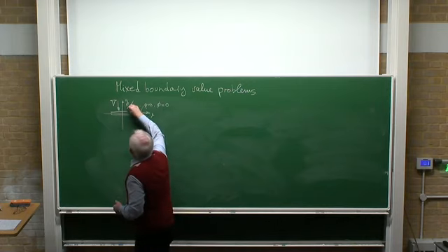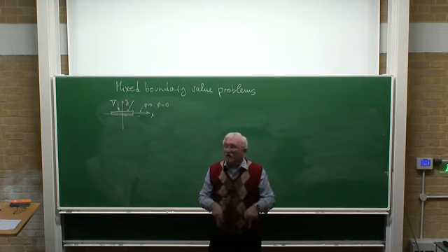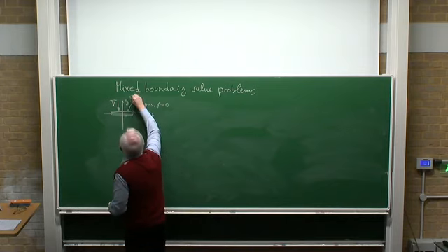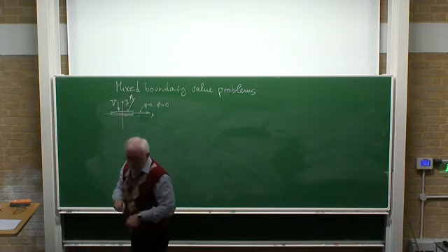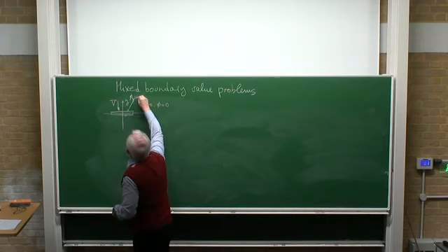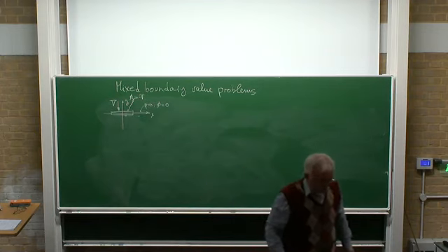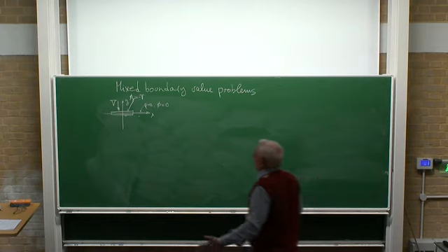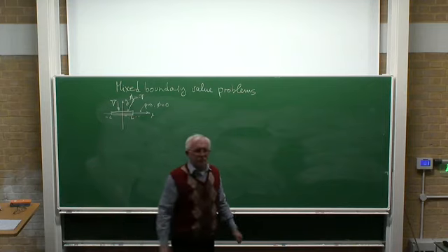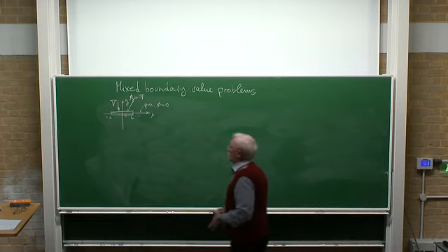Then over here, particles of liquid move with the same normal speed as the plate. So the boundary condition is vertical velocity, dphi/dy, where phi is the velocity potential, equal to minus v. Minus velocity because it's down. That is the boundary value problem we need to solve. Say that is the interval, that is the plate, from minus L to L, so total length is 2L.